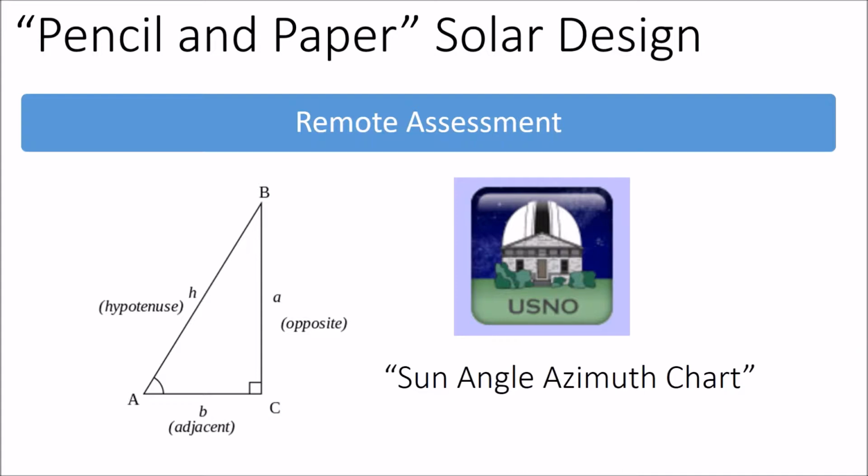Nowadays, that design process does not need to be so exact, because if you know that you're going to be on a rooftop that has partial shade conditions, you could specify DC optimizers on every other module, or microinverters on every module, and that would make every solar module on the rooftop its own individual system, so that the shaded modules would no longer drag down the unshaded modules. Or if you're just getting a tiny amount of shade from the early morning or late evening, something that's not on your array for the middle part of the day when the array is most productive, nowadays a string inverter with multiple power point tracking would be quite sufficient.